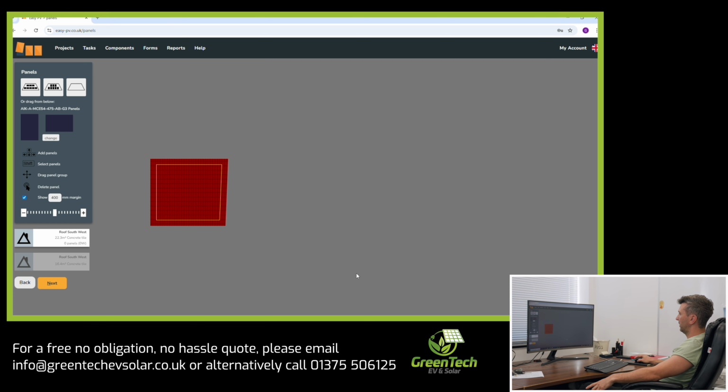We'll press select. And then it will give you a roof dimension here of what the satellite's already picked up. So you can drag the panels over like this and do it one by one, or you can just use these 2 here to have it on portrait or landscape to auto fill it for you. Sometimes you have to play a little bit about with it to maybe fit on a few more panels. The boundary there represents the 400mm boundary to keep within MCS regulations. So first, I think that may be better for a portrait design.